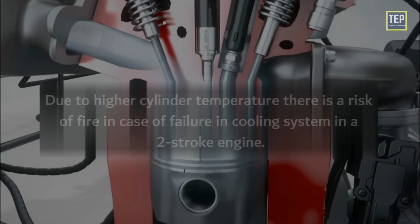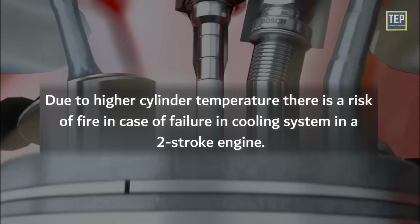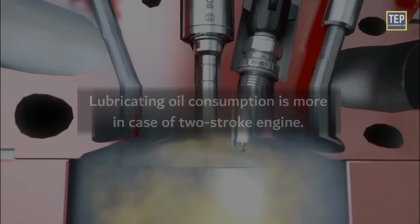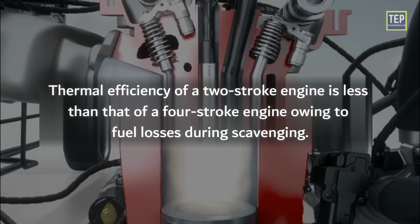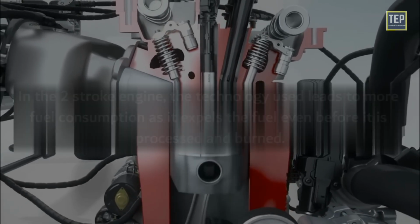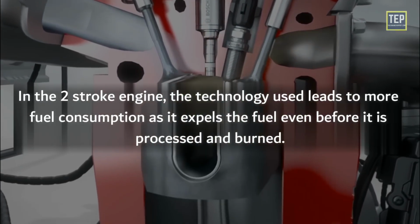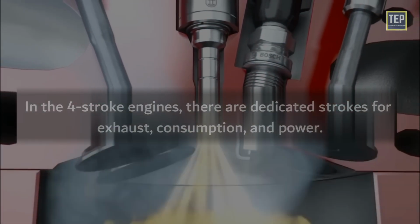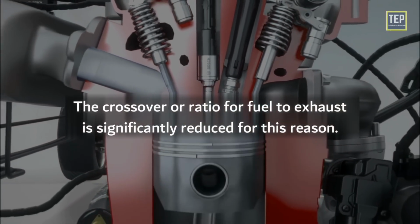Disadvantages. Due to higher cylinder temperature, there is a risk of fire in case of failure in the cooling system in a two-stroke engine. Lubricating oil consumption is more in a two-stroke engine. Thermal efficiency of a two-stroke engine is less than that of a four-stroke engine owing to fuel losses during scavenging. In the two-stroke engine, the technology used leads to more fuel consumption as it expels the fuel even before it is processed and burned. In four-stroke engines, there are dedicated strokes for intake, compression, power, and exhaust. The crossover or ratio of fuel to exhaust is significantly reduced for this reason.